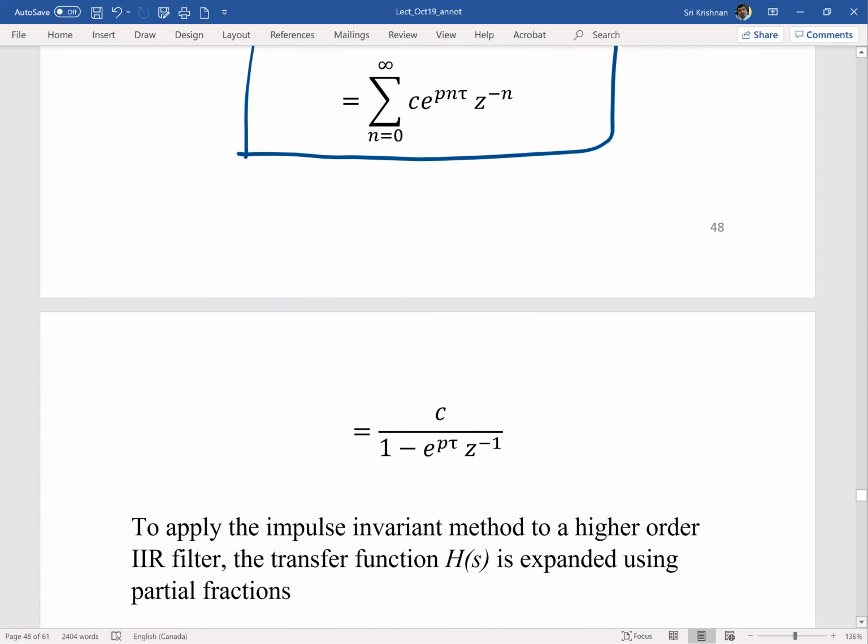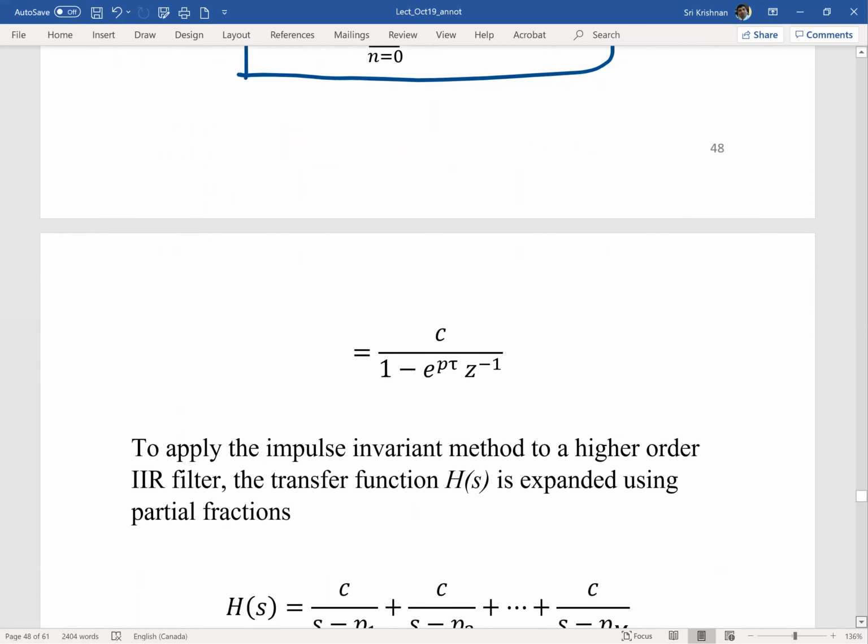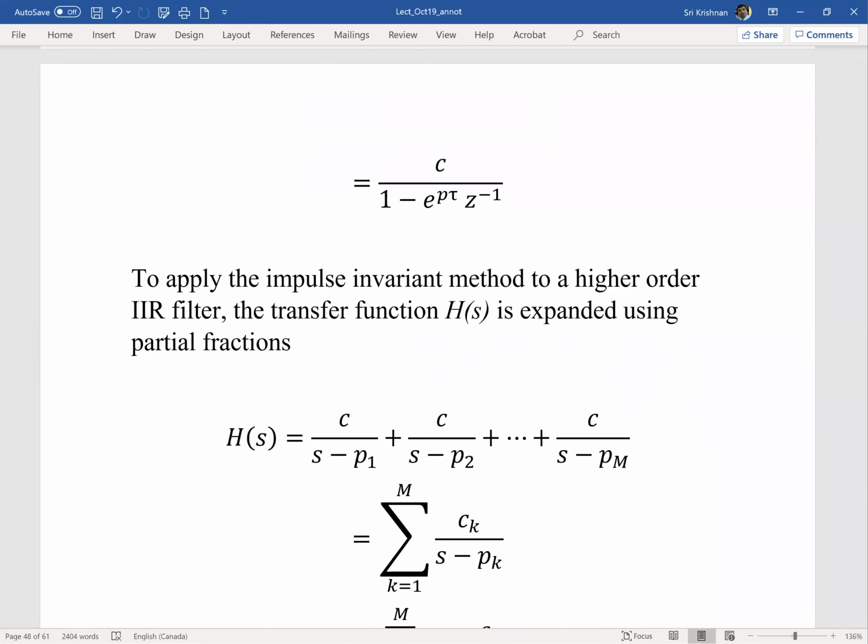Now, that summation translates to this expression, where it goes into the denominator, and you can very easily see we have a denominator notation here, which confirms the filter we are designing is definitely an IIR filter because it will bring poles into the system.